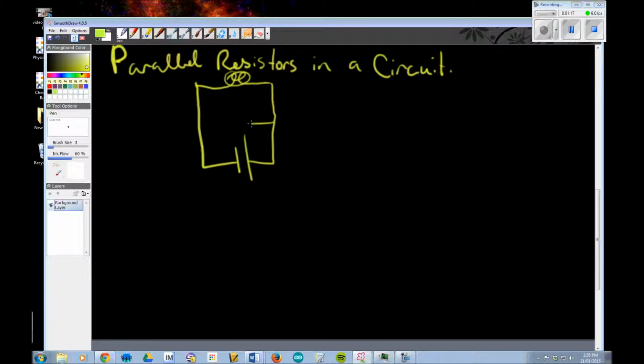If we add another resistor in parallel, we notice that both of these bulbs burn equally brightly, which is different than what happens if we put them in series, okay? We took our ammeter and we measured, and we found that with a 120 volt source, we had 0.6 amps traveling through this branch. We also had 0.6 amps traveling through this branch, and these were identical bulbs. And if we put an ammeter right here, we found that it was about 1.2 amps, so double, right?